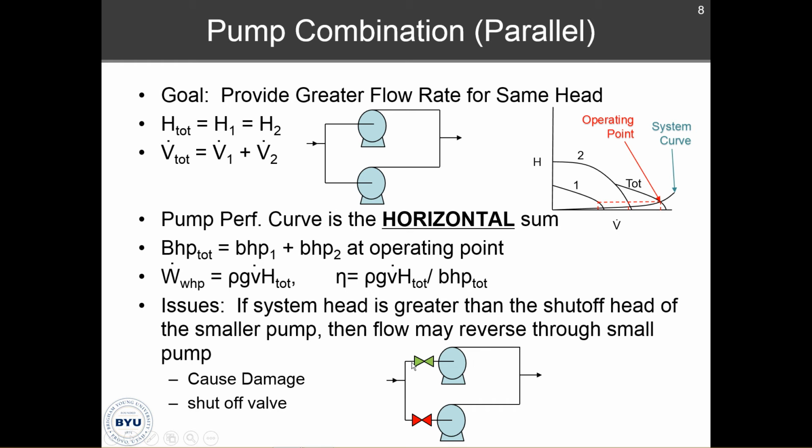So, just like with the pumps in series, what they do is they create a shutoff valve. This time we don't need a bypass valve because we're not trying to continue the flow to the network. We have a flow path through pump 1. What we do simply is shut off this valve so that there is no flow backwards, there is no pressure differential in that path, and then flow continues as normal through this path.